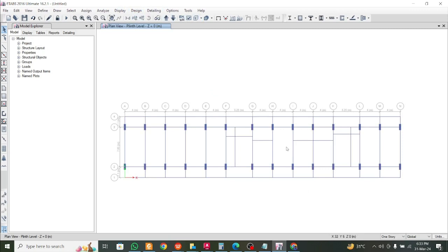Now we'll move on to the next portion which we need to complete, which is the next level. But before that, I think we can copy a significant portion of this to the next level here. So we'll copy this, and no need to press Ctrl. It's similar to AutoCAD. Instead, you need to press Ctrl. That's why I'm telling you, those who are STAAD users. So we'll copy the primary beams and not copy the column because they are already done. And this portion of secondary beams also, because this is for the staircase, this is also present in all the floors. So we'll copy this also.